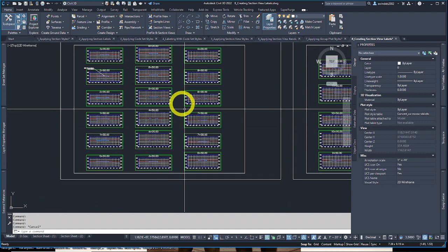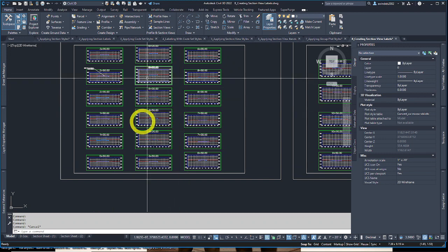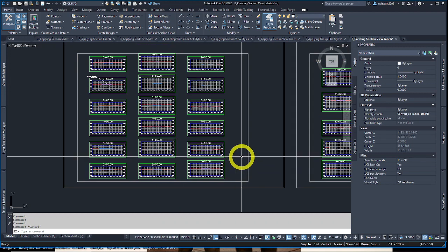Another difference is that section views are typically created in bulk amounts, a bunch of them in quantities. Unlike profile views, which stay along one alignment, parallel with it, section views run perpendicular to set alignments in many different views as they slice into it many different times. So think of them very similarly. On 208 we talk a little bit about sections. They are derived from surfaces. They're cut from surfaces. They can also be thought of as the same as surface profiles.